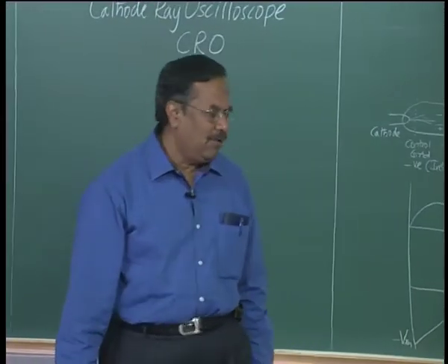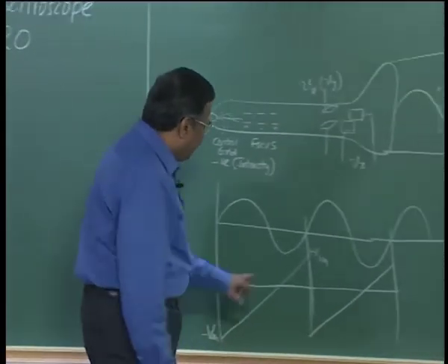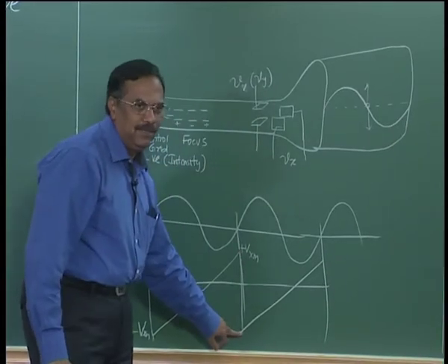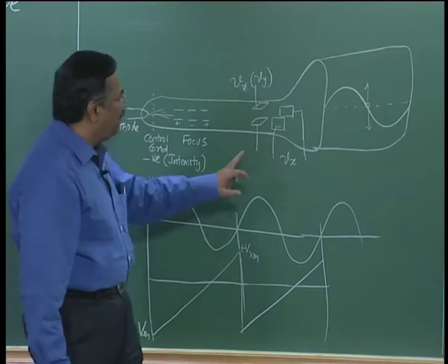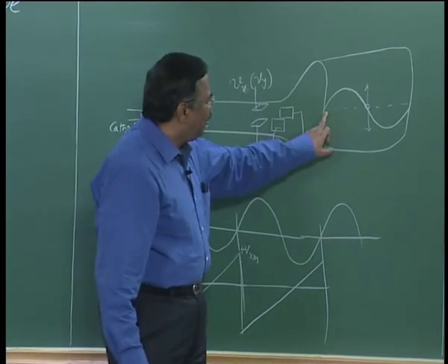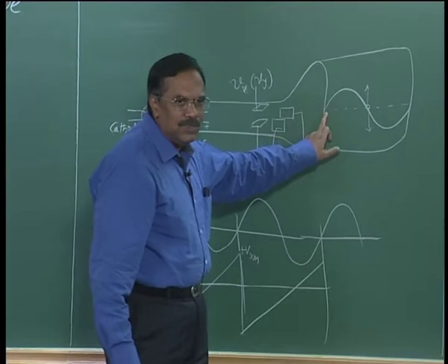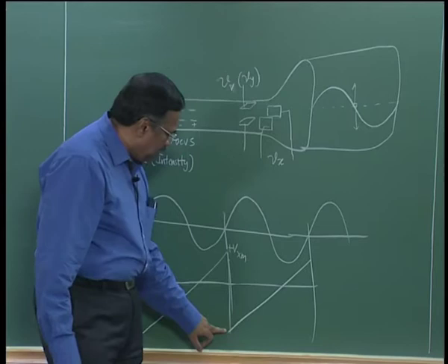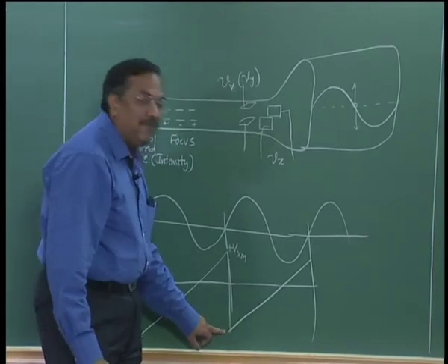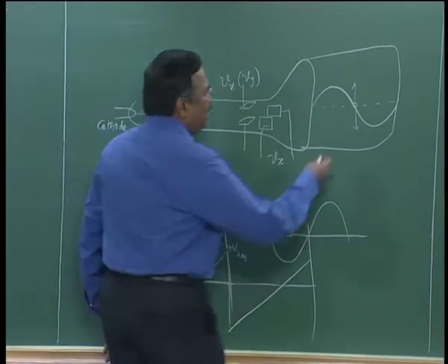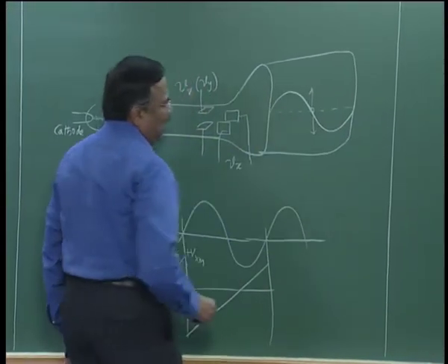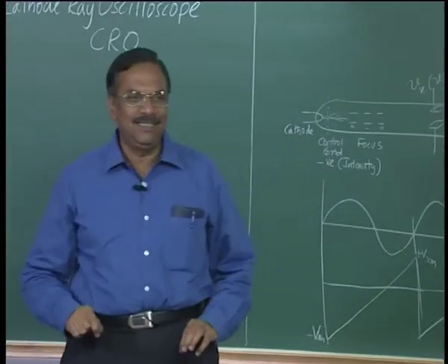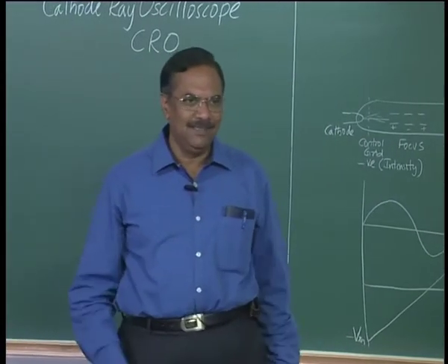And we also looked at when the sawtooth waveform goes from plus Vx max to minus Vx max at the end of one sweep, right. One sweep is the time taken for the spot to move from the leftmost in the x direction to the rightmost. At the end of one sweep, if we do not switch off, the electron beam would retrace its path, right, and you will see a faint horizontal line that is very distracting, it is not the signal, right.